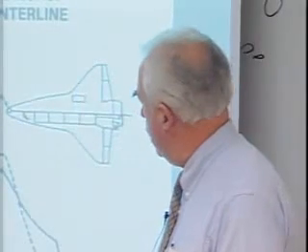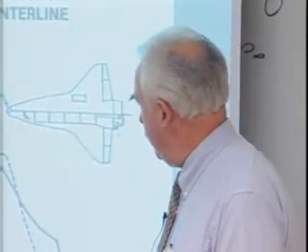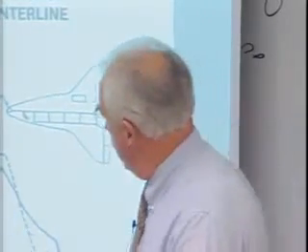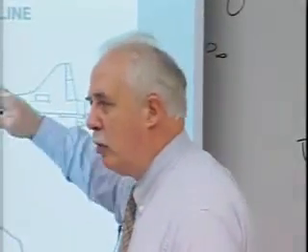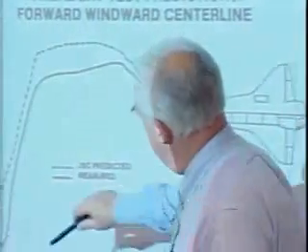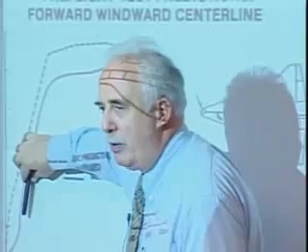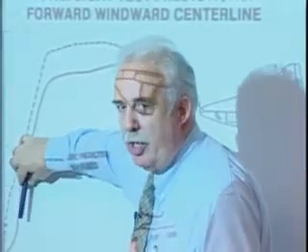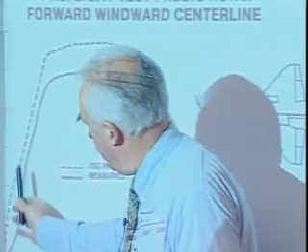Okay? Now, this is not what you'd see in a journal. I'll show you one you'd see in a journal here in the middle. This is right behind the carbon. Now, what we did is we computed at different times through the trajectory, and then there were correlations to get the history. The prediction, this is JSC prediction, is right here. Now, we didn't worry about exceeding Stanton number 1. That is, we didn't worry about the heat transfer being higher than the energy flux to the vehicle up here, because if you look at these numbers, we should have accounted for that, but it's not that important. So don't worry about that portion of the curve.